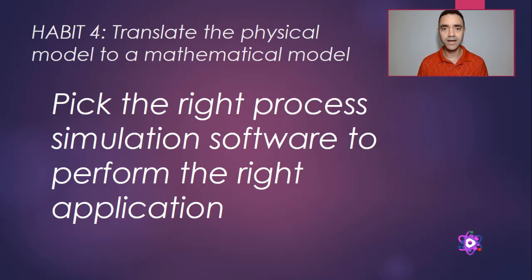For instance, Aspen HYSYS is well designed or fits best for hydrocarbon processing, while Aspen Plus fits better for chemical process. And if you need to perform a process simulation for a batch, you should not use Aspen HYSYS because it was not designed for that.